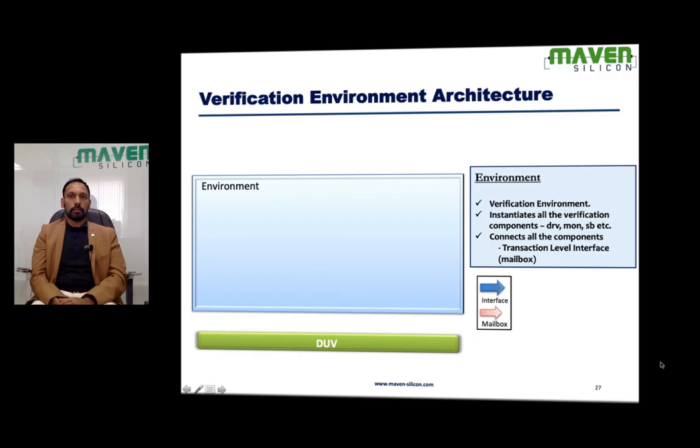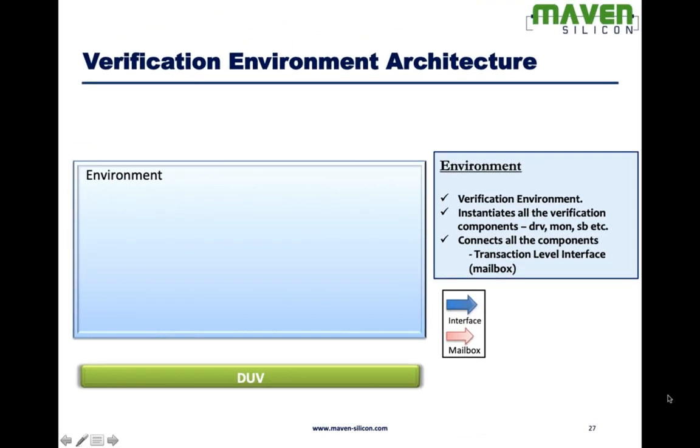Let's look at environment. It's called the verification environment. It's a top level test bench component. Basically, this top level test bench instantiates the lower level test bench components called transactors. All the transactors, drivers, monitors, generators, scoreboard, all the components will be instantiated within environment. And we connect all these components with the help of mailbox.